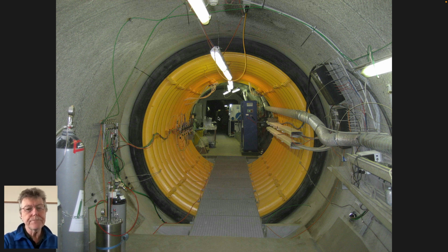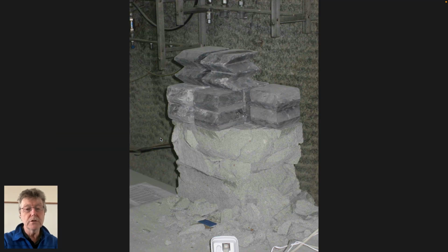So this is, we talked about packers, neoprene packers being inflated against a borehole. This is a borehole. It's actually a tunnel. This is a person's height. This is probably 6 feet tall. This is a ring that the neoprene is stretched against on the outside, with the idea that you can inflate it against the sides of this tunnel, and you can take water quality samples from the edge of it. So this whole length of this is going across a geological fault in this underground research lab. And the question is to look at what the characteristics of flow and transport are within this fault. And so one way to do that is hydraulically isolate the fault with a packer and do experiments that flow water along that.